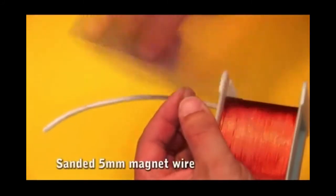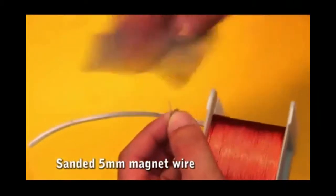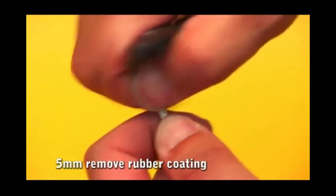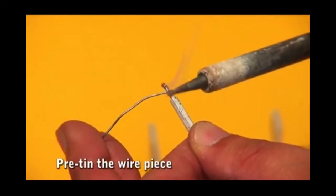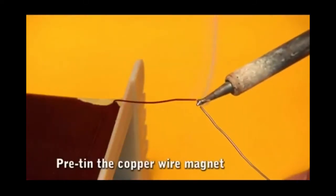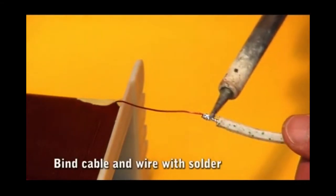We remove the dielectric varnish using a piece of sandpaper. We took a piece of cable and removed 5 mm of covering coating. Tin the tip of the cable. Tin the tip of the wire. And join the cable and wire with the soldering iron.